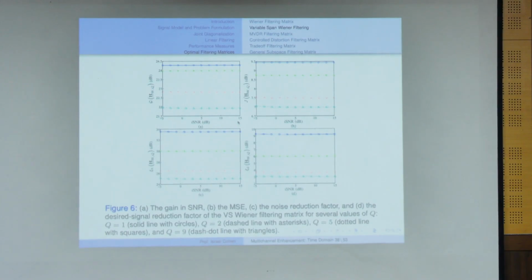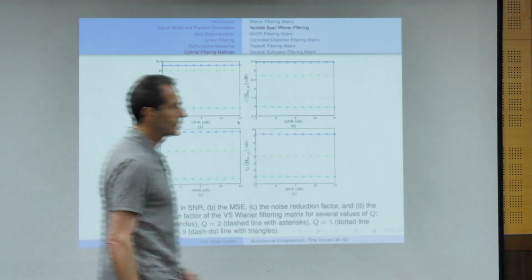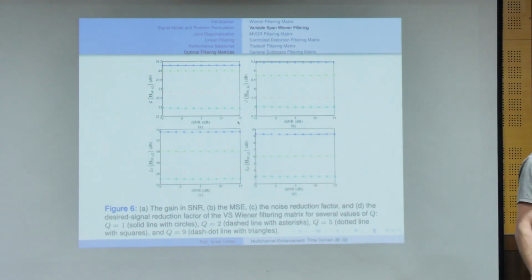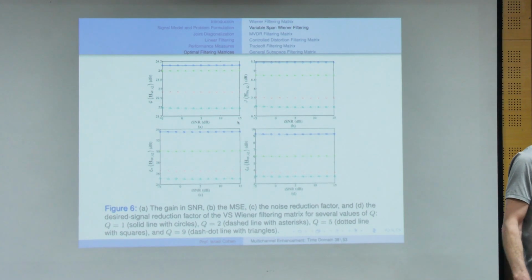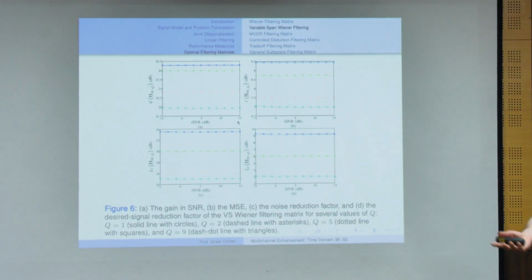But if one of the other sensors doesn't give you any information, then in the correlation matrix, you don't have any correlation. So it will not be used. This information is just like taking another sensor, and there is no correlation to the desired signal and no correlation to the noise. So it doesn't affect. It's just like removing it, okay?